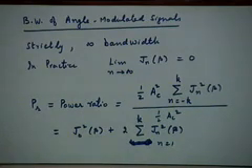So now the way we define the bandwidth is as follows. We agree that for a signal to have this bandwidth, whatever we define the bandwidth to be, it should have most of its energy in that band. The only thing we need to now quantify is the definition of most. So we can take some arbitrary figure, and a generally accepted figure is 98% bandwidth. So the way we define the 98% bandwidth of any signal, particularly signals which otherwise have infinite bandwidth, is that band of frequencies over which the signal contains 98% of its power.